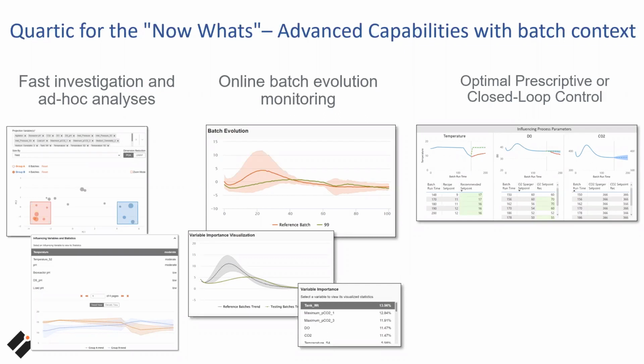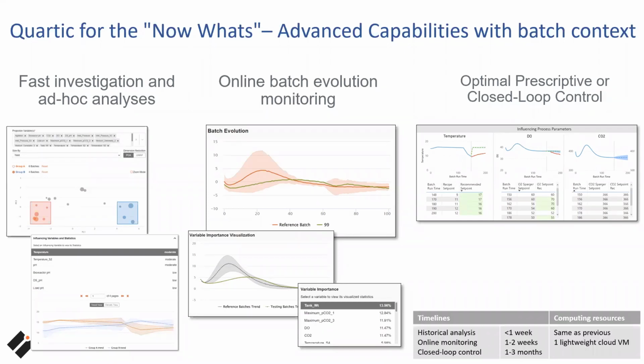And finally, on the right, you have optimal closed loop control. This algorithm is built for small data sets. Think a manufacturing process that may only run 10 batches per year. With the ability to overlay context, the time of sampling and PAT measurements can be aligned with other process data, and the optimizer can look at historical control and objective parameter measurements to recommend ideal set point changes for live batches. The Now What Narwhal now has direction as to how to use their digitized data and expand their analytical suite.